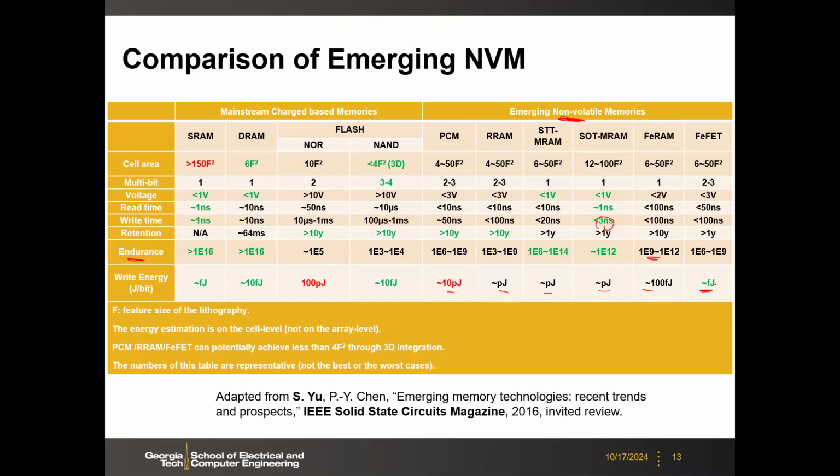So it's an electric field that flips the dipole. Then the power consumption is low. But other memories, especially phase change memory, as I said earlier, you need to locally heat up that material, right, to melt the material. So you need to pass large current to do the Joule heating. So that's why the energy consumption to write the data is very high.